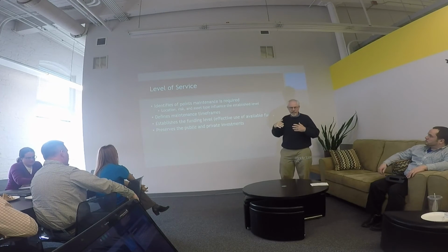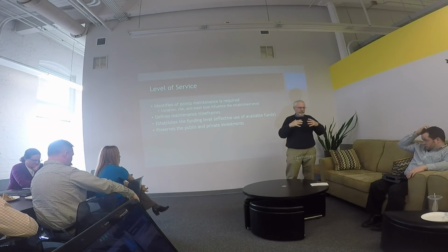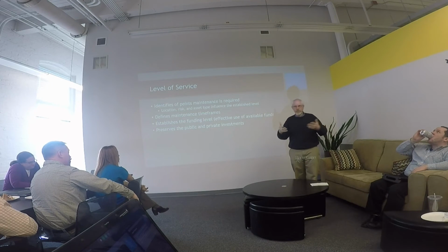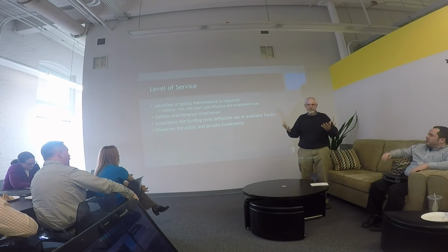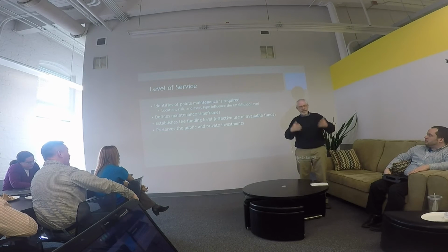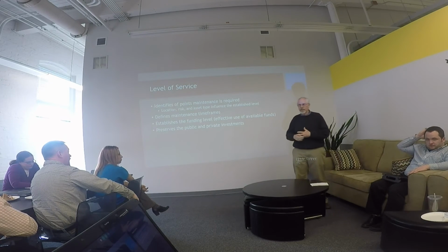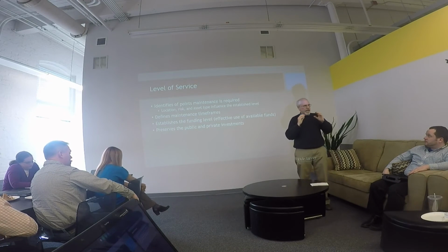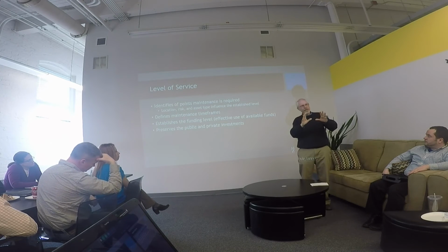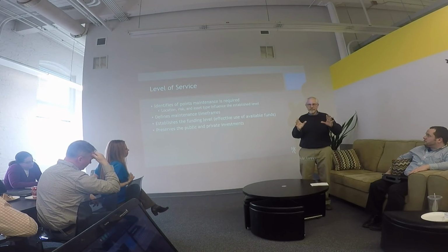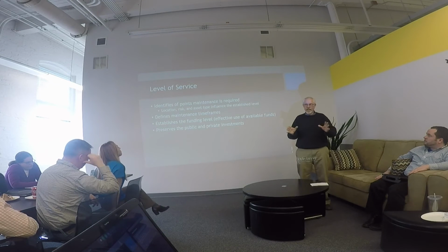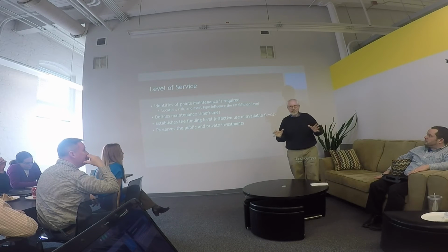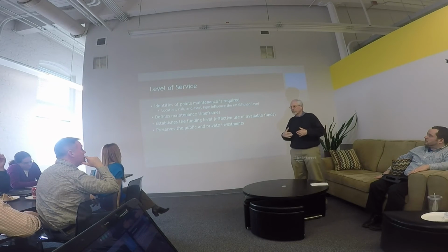Level of service. Level of service is either a system-wide level of service, like if you're doing a water system, our level of service is we promise not to poison you. So in other words, we'll meet all the compliance and the regulatory, and we'll make sure that you have at least 35 PSI at your faucet, because that's the minimum requirement. I would say that most of you don't have that because you wouldn't be happy with it. So that's not a very good level of service.